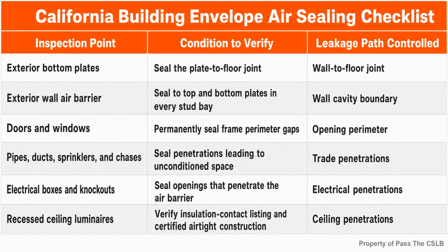I also keep envelope leakage separate from duct leakage. The blower door measurement addresses the boundary around conditioned space. A duct leakage test isolates and pressurizes the heating and cooling duct system. Both involve air pressure, but they evaluate different systems and report different information. That distinction matters during troubleshooting. A high enclosure leakage result sends attention toward the building boundary. A duct leakage problem sends attention toward the duct network and its connections. Confusing the two can send the repair crew into the wrong part of the project.